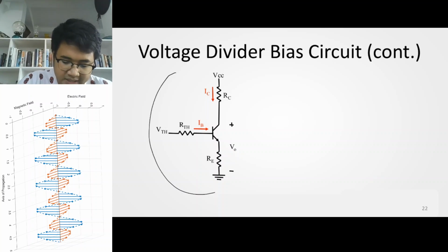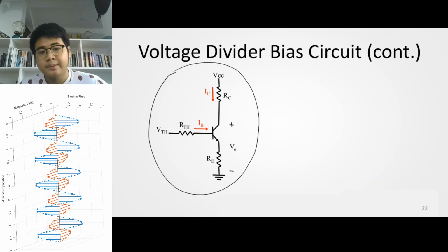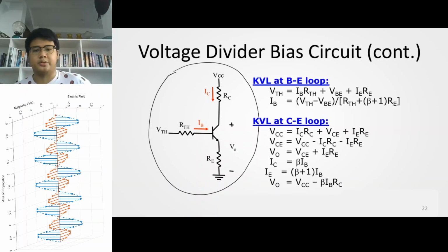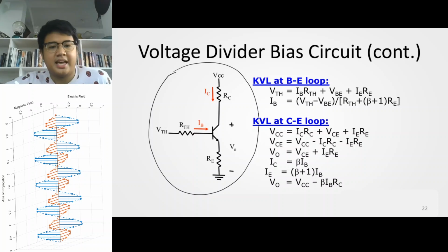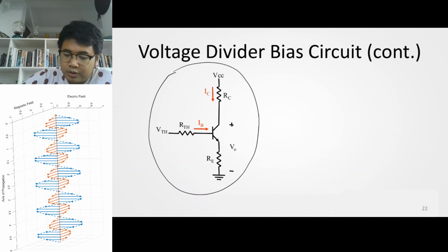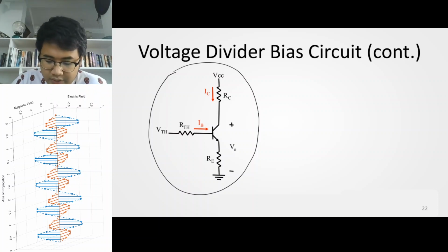with this simplified circuit on the left, and we can now analyze V out as such. Okay? So using KVL and KCL, you can analyze this. But again, I prefer nodal analysis. And if you're not yet comfortable with this notation on the left-hand side of the screen, I suggest you convert the circuit to the equivalent circuit of the transistor.